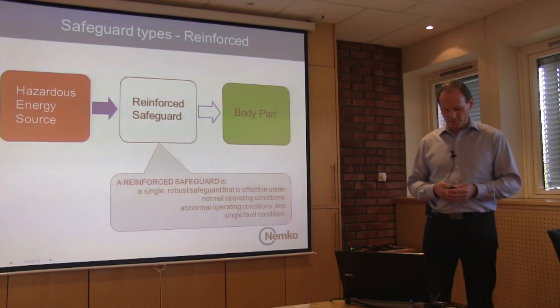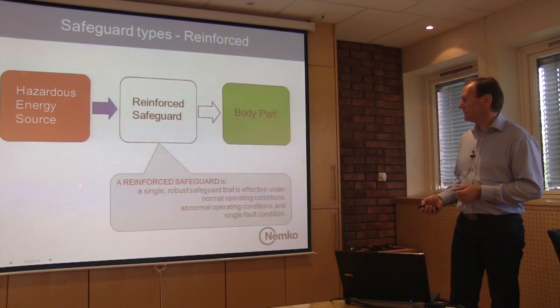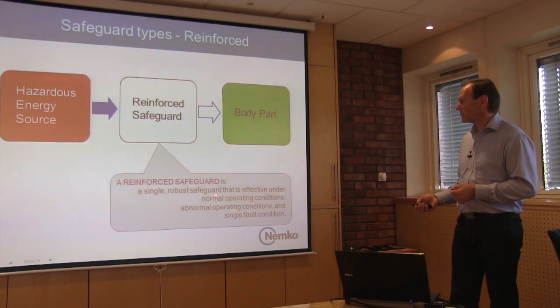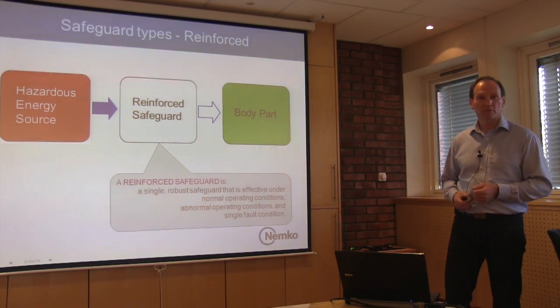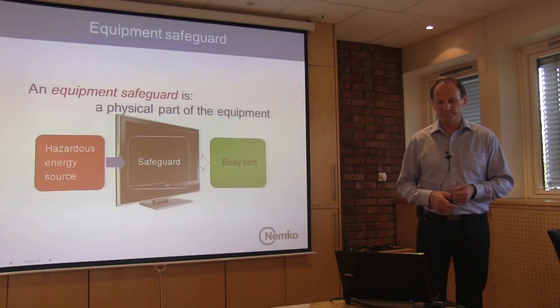So then you have the reinforced safeguard. That's the same as we have for double insulation. A reinforced safeguard is a single robust safeguard that is effective under normal operating conditions, abnormal, and single fault conditions. That's what we have today.